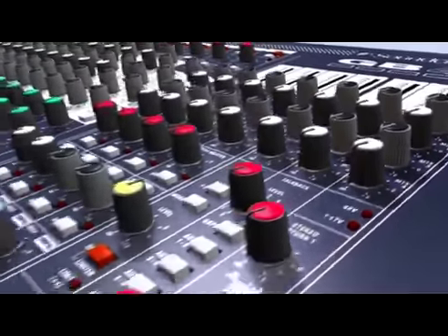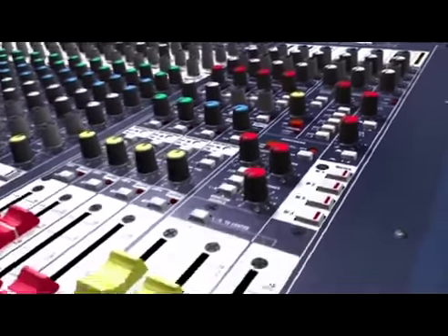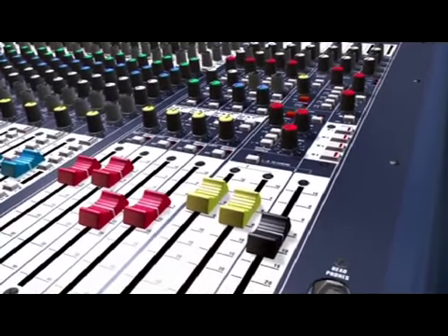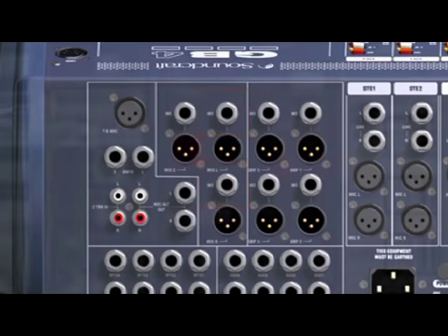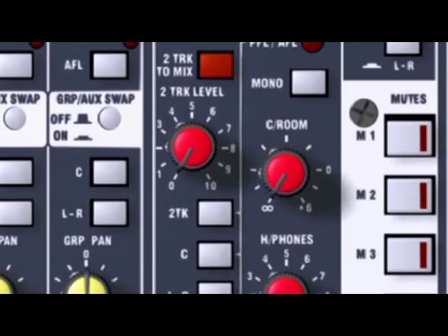The master section is where you control and monitor the mix and where you send it to its various destinations. Mix outputs control the level of the final stereo mix. You may find your mixer has mix insert points, which would be useful if you needed to connect signal processors across the whole mix. The control room or engineer's outputs are not sent to the auditorium, but are normally used for an engineer's headphone feed or loudspeakers in a control room. You can monitor the whole mix from here, or any solo, submix from a group, or 2-track tape return.